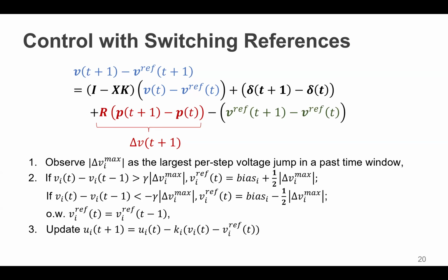And then the follow-up question: is this voltage instantaneous, or is it actually the average? Phasor or...? For that linear flow model, that could be understood as a kind of average voltage within some period. So that is the time horizon for the linear flow to model the voltage. The finer time scale, within milliseconds, requires some power electronics side of modeling to capture this impact. So that is definitely a gap we want to fill.